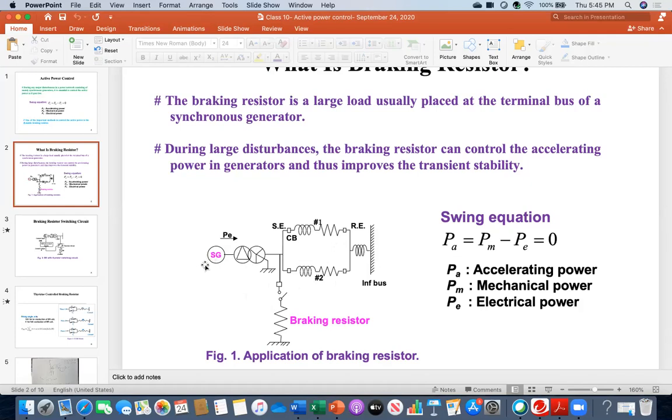If the shaft accelerates, or decelerates in case of a negative value, then your frequency will change, throughout the network, even on the customer side. Therefore, first you have to control the machine and return it back.